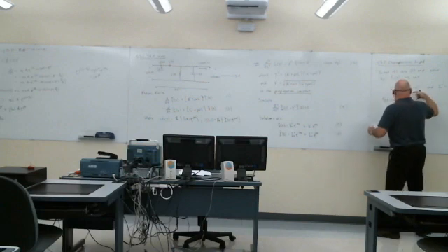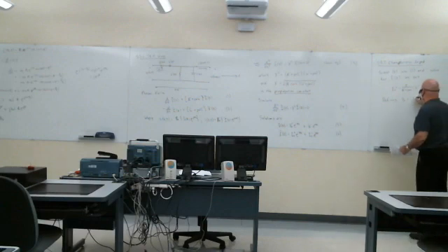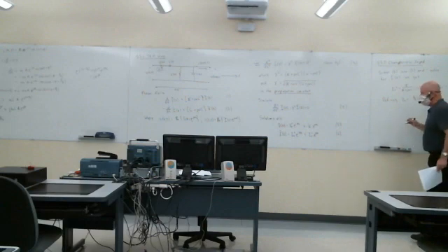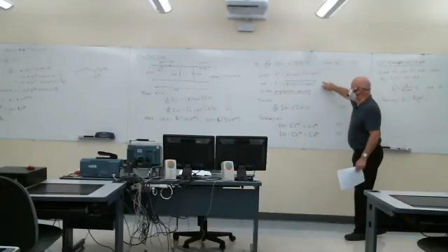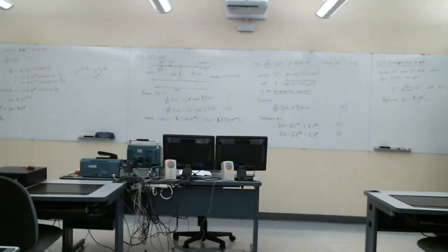We want the ratio of V to I as an impedance. So the impedance would actually be the reciprocal of this, R prime plus j omega L prime over gamma. If you take our expression for gamma, it's the square root of R prime plus j omega L prime times G prime plus j omega C prime.